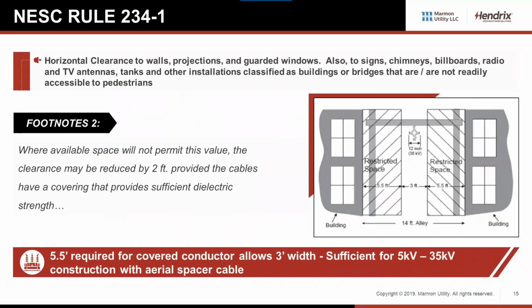NESC rule 234-1, we always try to point this out. This is really one of the big advantages in more of a municipal environment. Horizontal clearance to man-made structures like buildings, billboards, different radio and TV antennas. You can reduce the required spacing by the NESC by 2 feet.